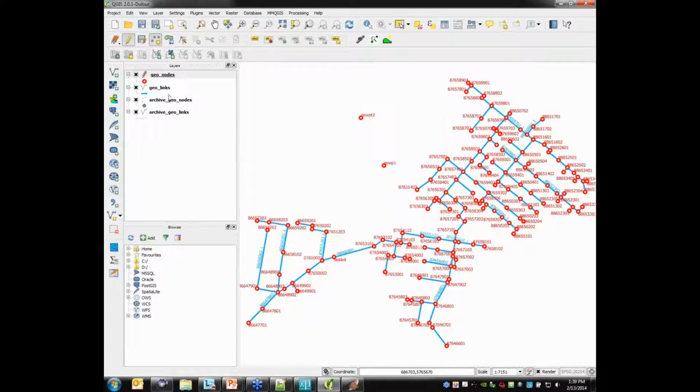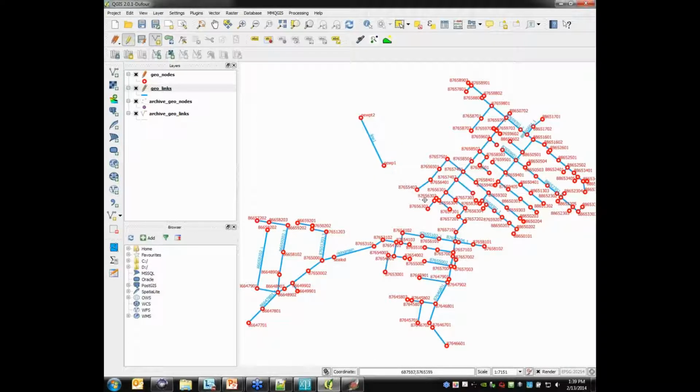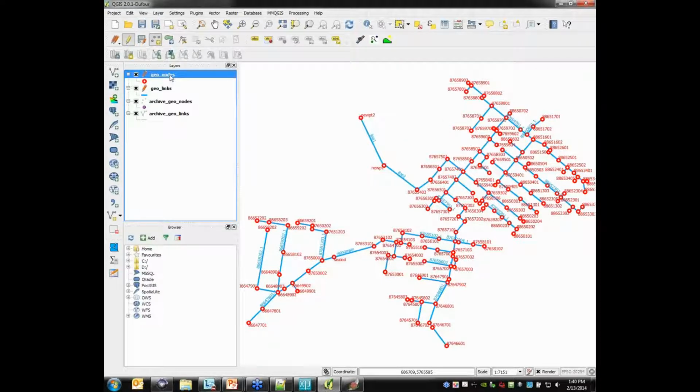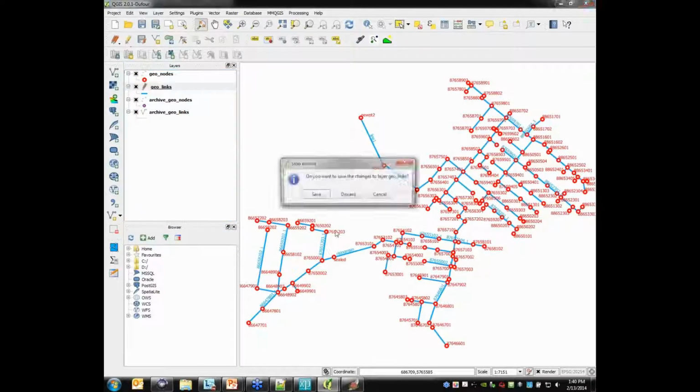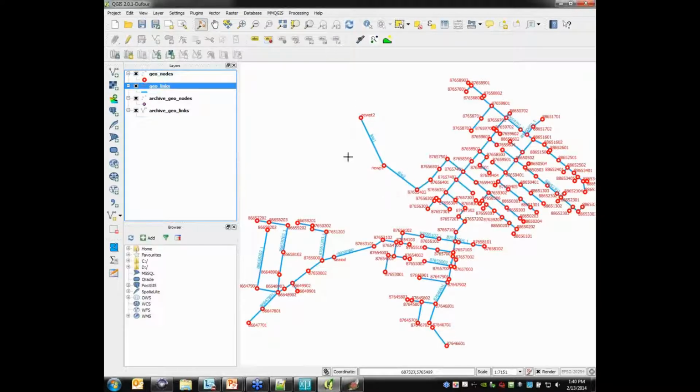And let's say I want to add some links to connect those. I'm going to add a line from here to here, and I'll call it line 1, and I'll give it a diameter. Notice how little information I actually have to give it to be able to generate that. It's kind of the value of a spatial database. Line 2, and then say a diameter of 1.1. As a nice general concept, it's useful to export nodes first and then export links. And similarly, it's useful to save nodes first and then save links. That's just something that is a good rule of thumb, just because generally this defines itself based on where it is. I have these 2 lines here.